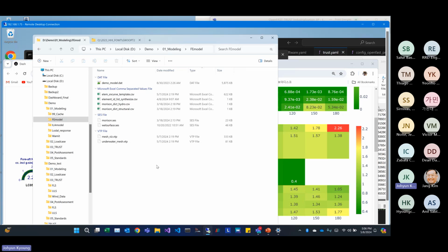This is the same as the OpenFAST analysis. OpenFAST uses the pressure mapping below the mean water level using the WAMIT pressure output, right? Yeah, same pressure mapping to the structure in the pre-processing, and later using the wave elevation, it generates the structural response directly. Got it. Thank you. I appreciate it.